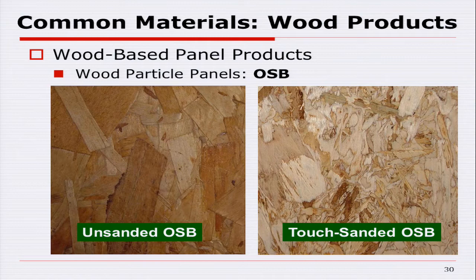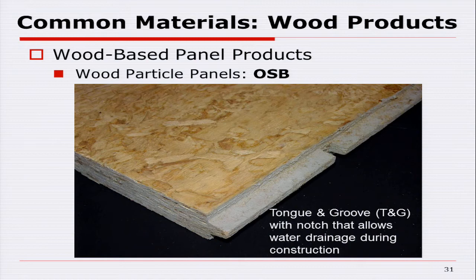They'll fall out. Once it goes through the strander and we strand this whole log up, we screen it so all that fine stuff like those knots falls out and we're just left with these nice strands. So you get back to formation: you lay strands one way, you lay them the next way, and you can lay another layer this way and so forth. You alternate them. That's why it's called oriented strand board, because you're orienting those strands as you put this together. Then you press it all together. It's got adhesive, you press it together with heat, and you get your panel. We'll pass those around in a second.